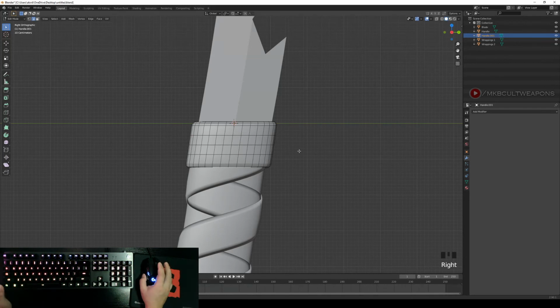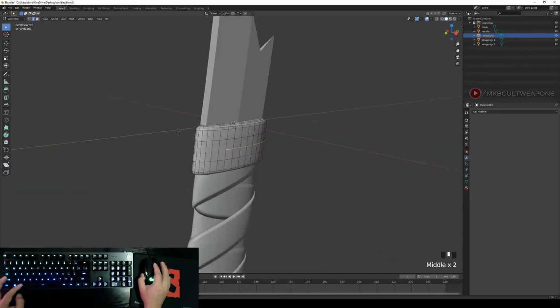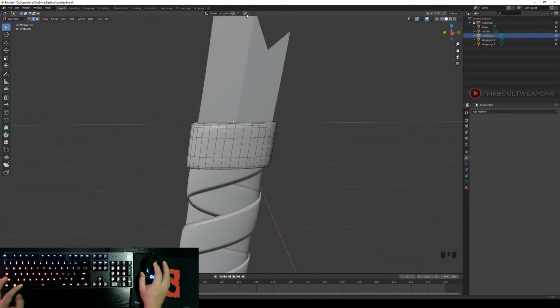Now the next thing we're going to do is just select all the edge in between, Shift Alt, and then select a single edge over here so that we could select every edge around this part at least. Then go to proportional editing again, press S to scale. Let's just go up to this point.